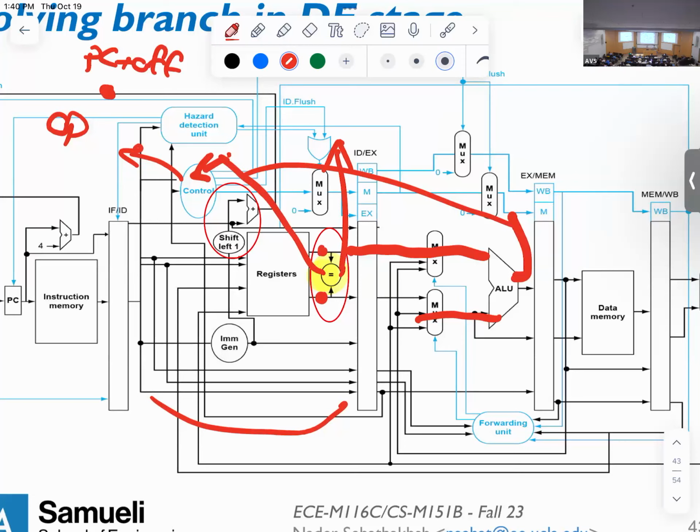So now that we're no longer doing that computation in the execute stage, what happens when we get a zero from the ALU? The question is, what happens to the zero? I'm just getting rid of the zero. I no longer need it, right? So the cost that I'm paying is that I'm adding a mini ALU in the decode stage. I'm getting rid of the zero completely.